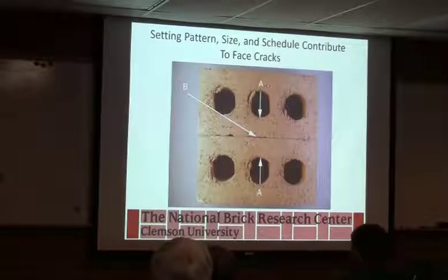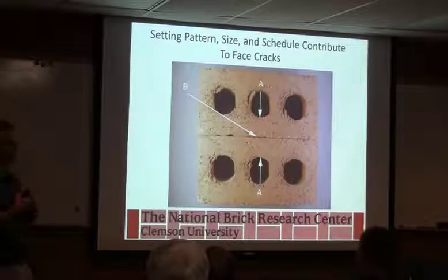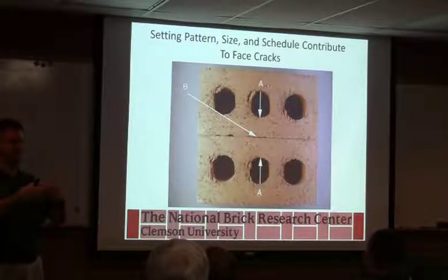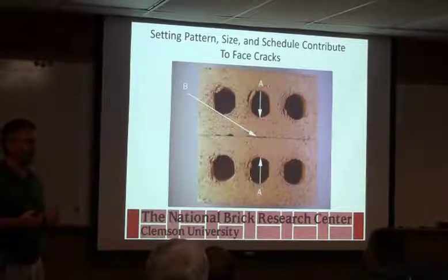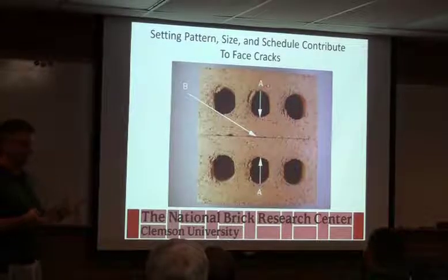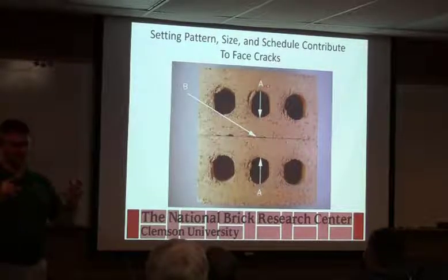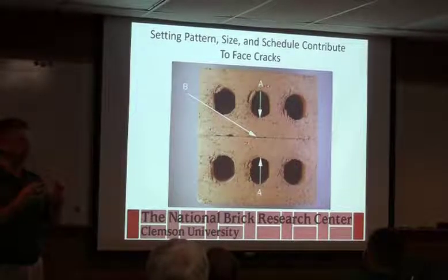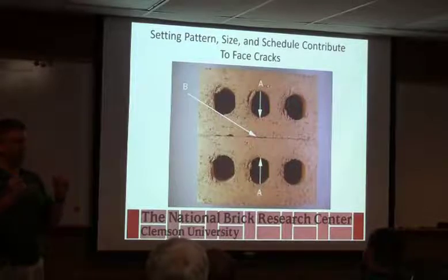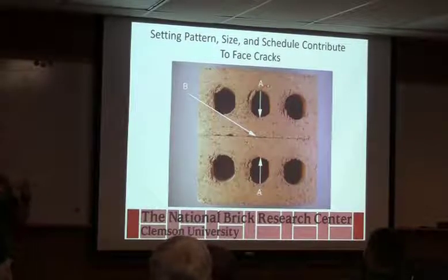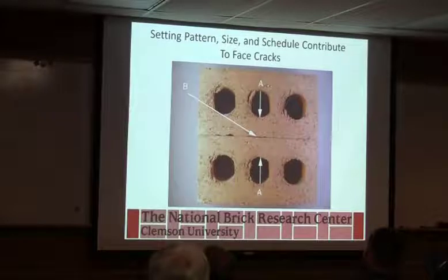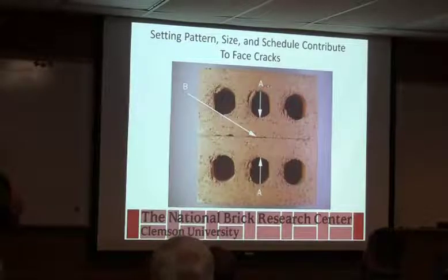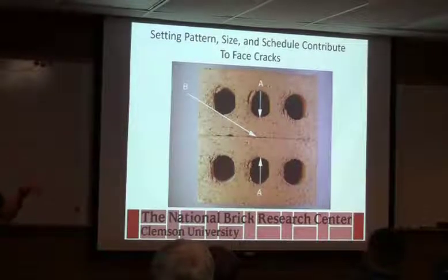Usually when you start forming cracks, it's because something is producing a differential across the product. If it's in the firing, you're possibly shrinking one part of it before the other, and it's trying to catch up and putting stress on it. Typically, when you start firing a brick, you put the outside in tension and the inside in compression, because you're only shrinking the outside shell of it.